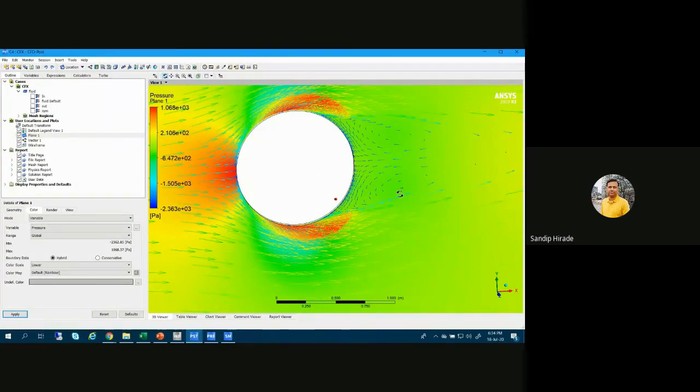Yes. Partial differential equations are basically transformed into analytical equations based on your grid. When your grid or domain is discretized, you convert the partial differential equation into analytical equations. For a smaller domain, or for elements, you just convert the domain into small rectangular elements, and then you convert the partial differential equation into analytical equations.